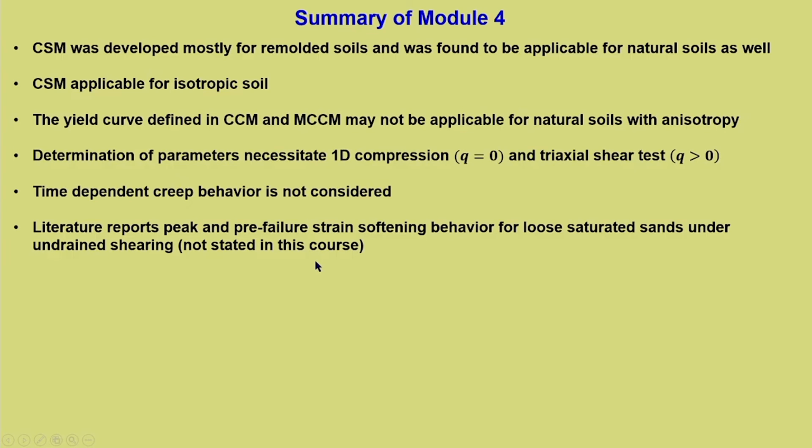Now we have always gone by the notion that the peak is always related to a dense state of the sand or overconsolidated soil, but there are results in the literature wherein the peak is also reported for loose saturated sand, and that too under undrained condition. Why we did not discuss this is that for sands generally the undrained condition is not that prominent unless we talk about liquefaction.